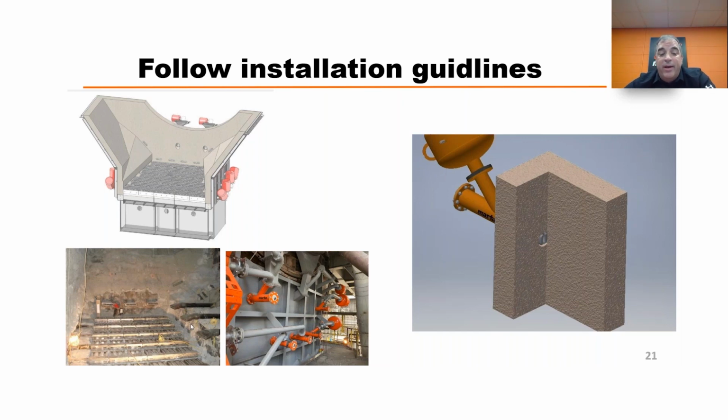They don't really care, and it is very, very easy to get a nozzle installed incorrectly, and then basically everyone thinks the cannon isn't working, but it's not installed correctly. So as your guys go out and look, determine what sort of nozzles you're using, whether they're pipes, whether they're fan nozzles, and where they're located on the system.